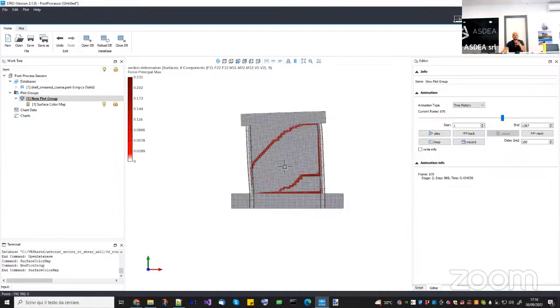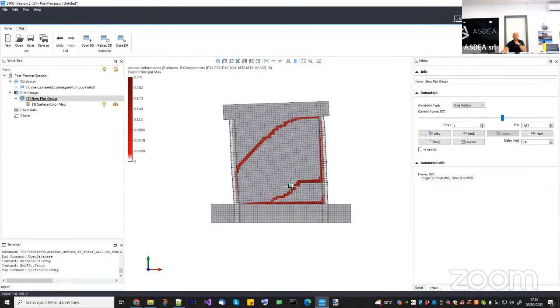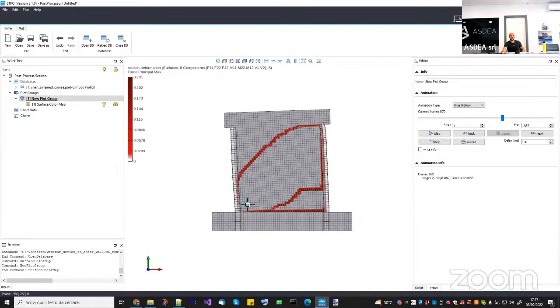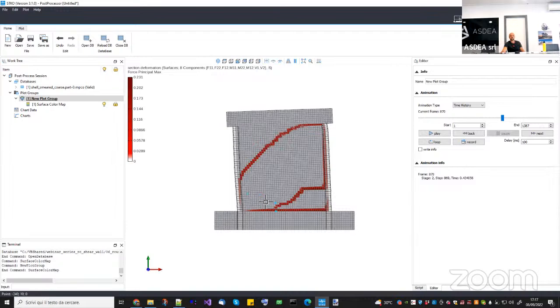So this is one of the first problems that you may encounter with strain softening, which is the size effect. So you either model the microstructure, as I've shown, for example, modeling the rebars physically and using the embedded condition, but then the model becomes very complicated. Or if you want to use a smeared approach, my suggestion would be to have a mesh size which is comparable with the microstructure. Okay, pretty much the size of the microstructure.